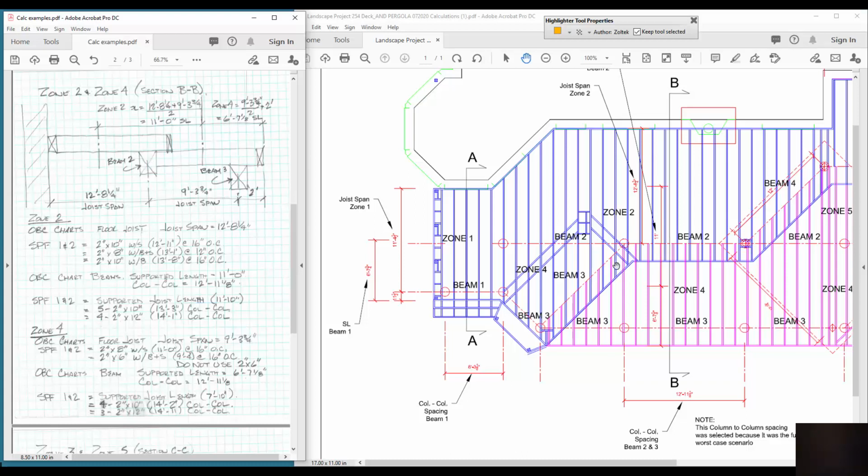If we take a look at this, the magenta part of the deck is supported to the side of the beam and then on top of the beam in the lower section. Let's see if I can represent some of this here in color just to give us some variation. That is represented by the top portion of it. That's what that joist represents right along here.